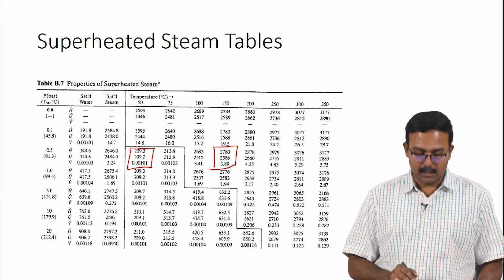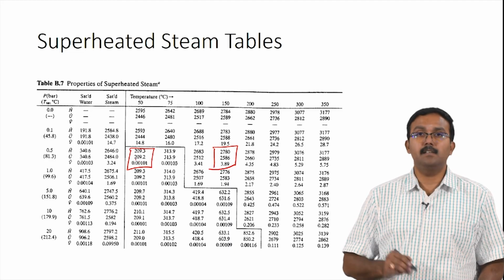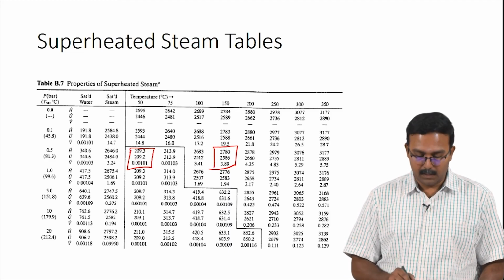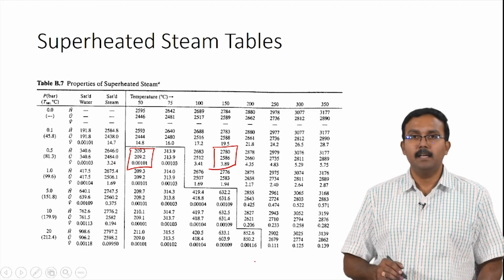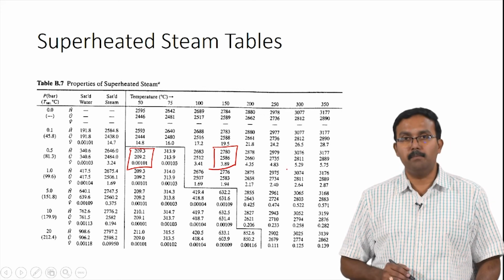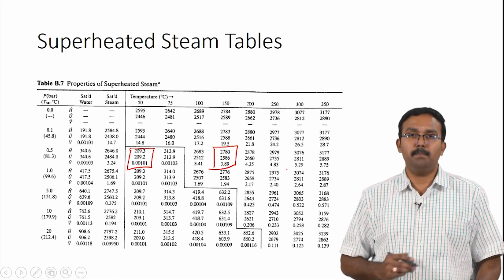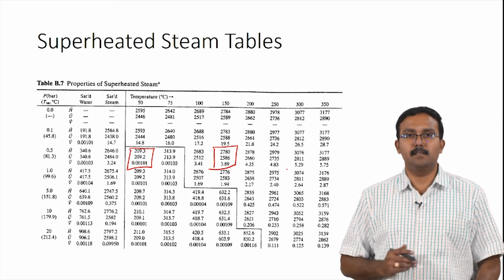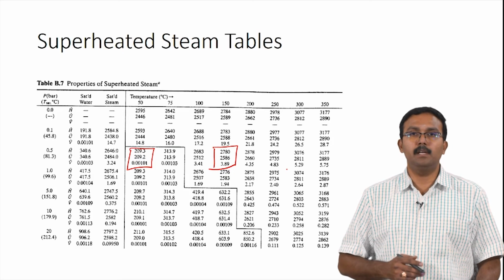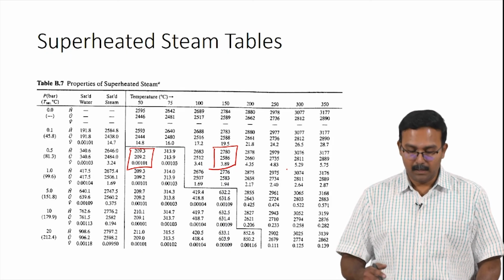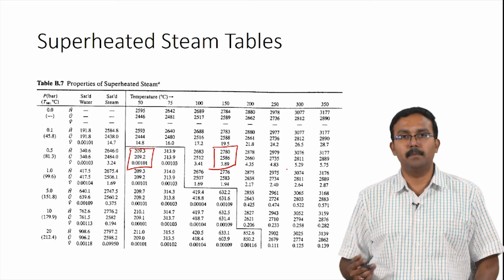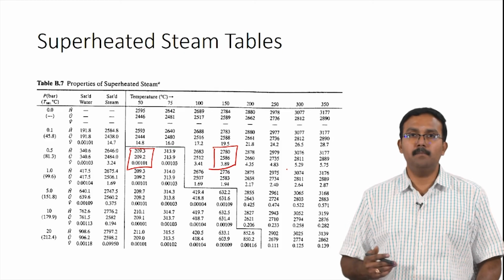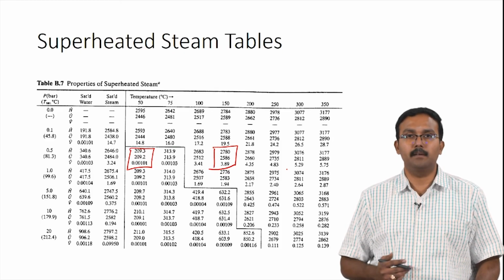So, whatever conditions in which water exists only as liquid are covered within this step shaped box. Everything outside of the step shaped box is a vapor condition. So, within the box you have only liquid existing, which is called either a subcooled liquid or liquid, and outside of it is called the superheated steam, where you have only steam and it is not in equilibrium with anything.